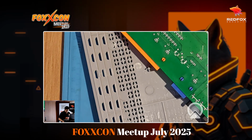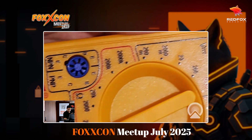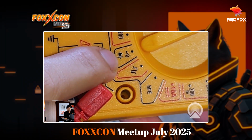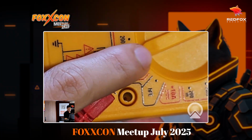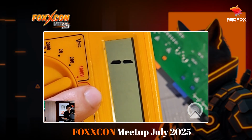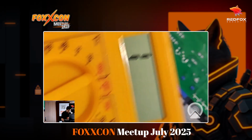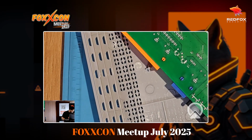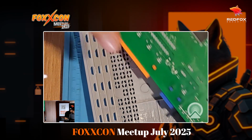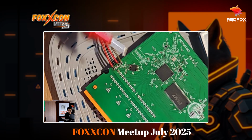We just take a multimeter, we put it on continuity mode, which is this mode, which shows you if electricity is flowing from one end to the other. You see the arrow points there. Okay, and if you hear a beep on here, or if you see 1 or 0 here, that means electricity is flowing. Okay, so I'll just do that quickly. First we'll just try out, let's say, the first connector that we have out here, which is this one. Second.